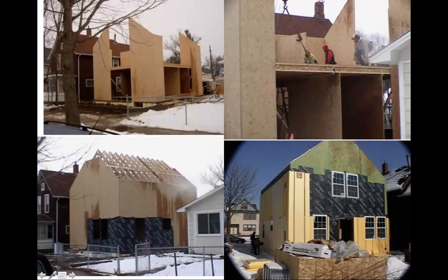So this I-beam, as I'm showing with the pointer, actually extends over, attaches to this wall, and keeps that wall from buckling out or buckling in. So in a sense, this flooring system ends up serving two functions. In addition to supporting the load up above, it also is the buckling support for this, so that the height of this column is actually much less.